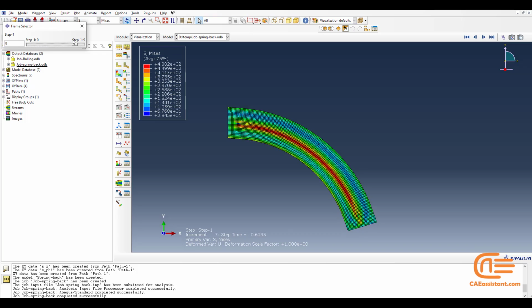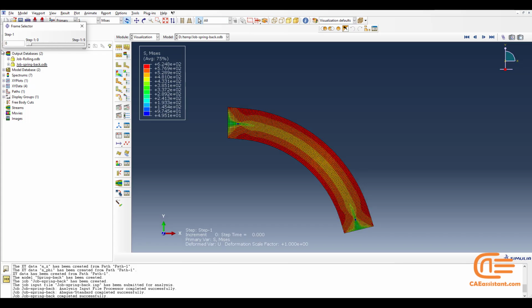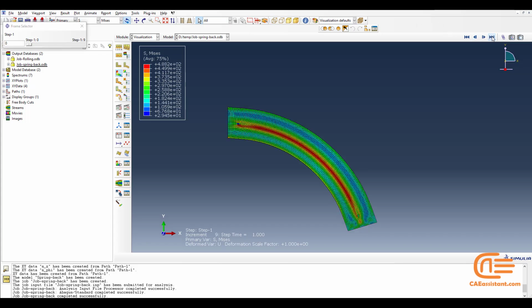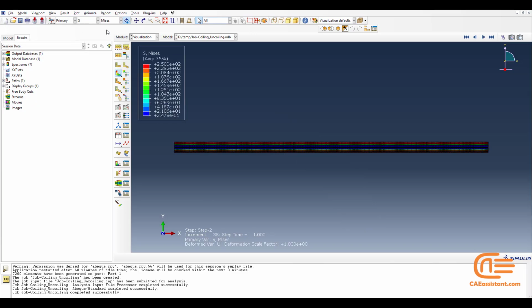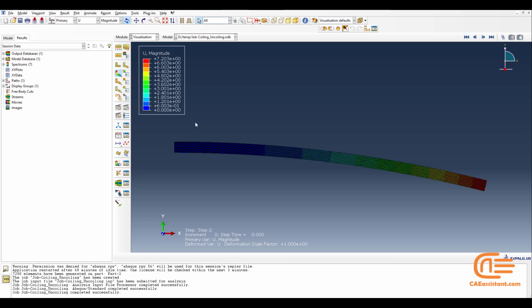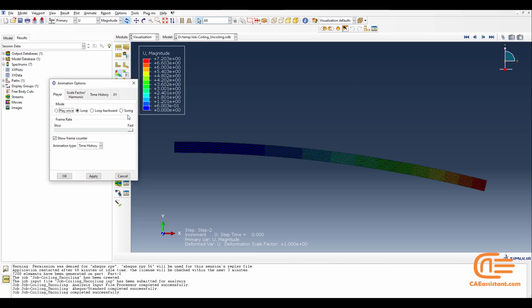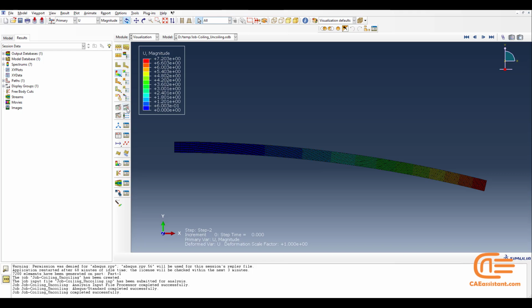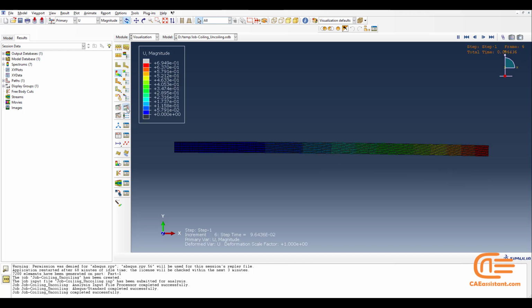Numerical simulations offer a solution for cold-forming residual stress analysis. Among the available numerical methods, Abaqus cold forming simulation has gained significant attention from researchers and practitioners. The residual stresses resulting from cold forming exhibit a nonlinear variation across the thickness of the section. They significantly impact the mechanical behavior of structural members made from cold formed sections.